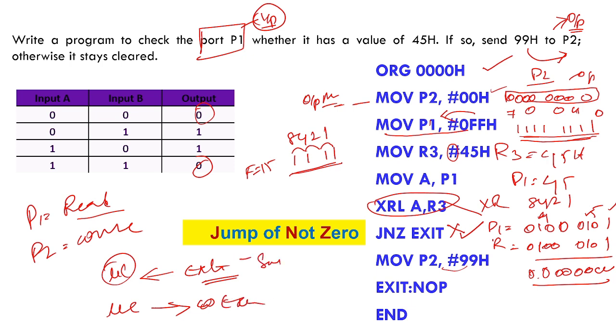Here this is a switch. Here I configured an input port. Here this is an external device configured as an output port. Okay, so this is a very simple program to understand the bit level logic. So ports also you can understand. So repeating again, to configure any port as an input, you give FF. If I want to configure any port as output, you need to give the immediate value of 00H.